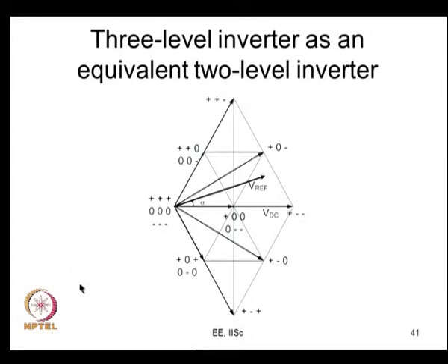Now, coming back to what we are trying to do, I am showing a part of the picture. I am not showing all the 6 sectors, but only this region now. There are certain things you can always observe. Let us say the reference vector is somewhere within this part. You will see that the R phase is predominantly positive, or R is 0, and the Y phase predominantly switches between minus and plus, with some limited variation. Okay. So, let us now look at this hexagon.